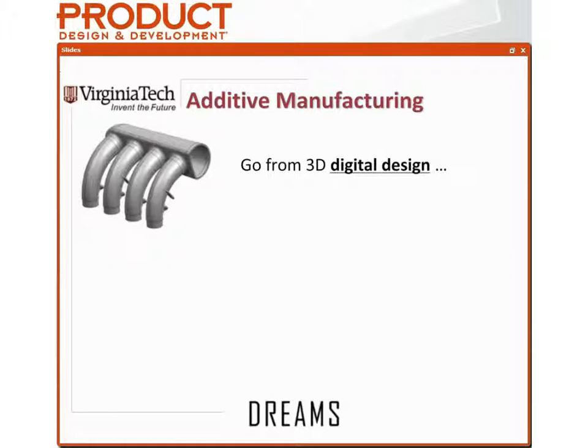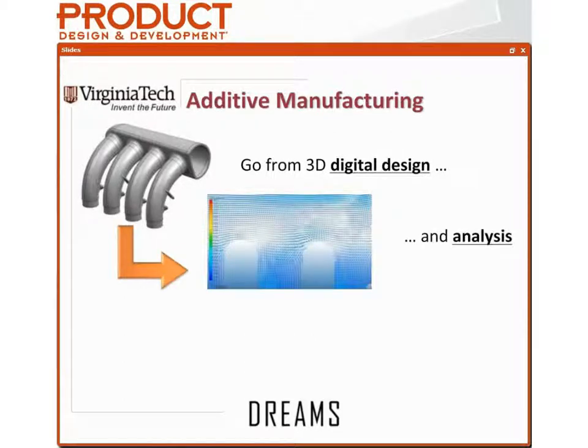This is a project by a student of mine who actually wanted to make directly his intake manifold to the engine. So he had this design which had tapered runners to provide equal airflow to all cylinder heads. It had a tapered plenum. It was a design that just couldn't be manufactured with traditional aluminum extrusion and welding. So he had designed the product.